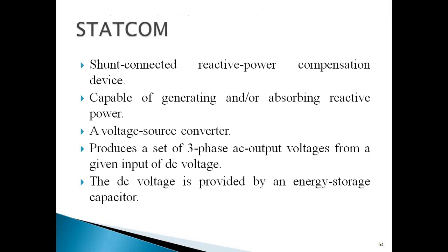So this concept is very important. STATCOM, I'll take time to explain in detail. So STATCOM is nothing but static synchronous compensator. It is shunt connected. It is a reactive power compensating device. It has got both the capability of generating as well as absorbing reactive power. It is modeled as a voltage source converter, or it will act as a voltage source.